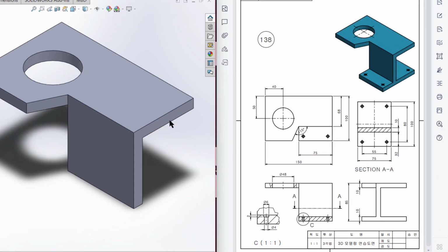So then in our shape we can see the section A view. If we see the section A view, we have a rectangular shape, and this rectangular shape, if we see from the top view, this is our rectangular shape, and it has a dimension of 75 by 100 unit, and it has extrude boss of 10 unit. So let's draw it.